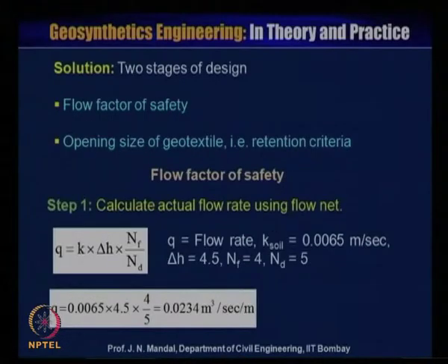Now the solution. When you solve this kind of problem, there are two stages of design. One is the flow factor of safety, the other is the retention criteria, that means what should be the opening size of the geotextile, and what will be the ultimate flow factor of safety.